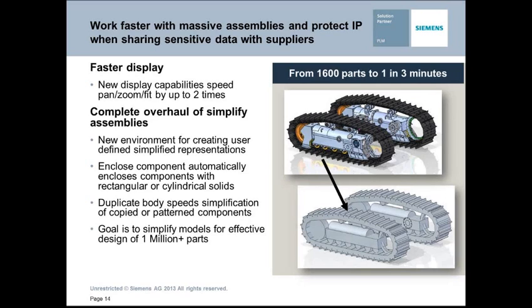This one, oh man, this is a demo that requires a demonstration all for itself. Simplify assemblies. Everybody's been asking about it. It gives us the ability to take a large amount of parts and replace them with simple bodies for use inside our assemblies. And what this does is enhance our assembly model to be able to support up to 1 million parts.